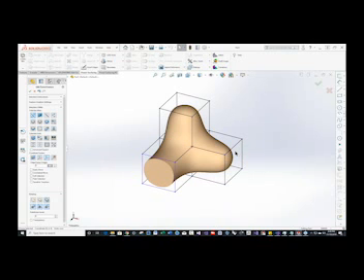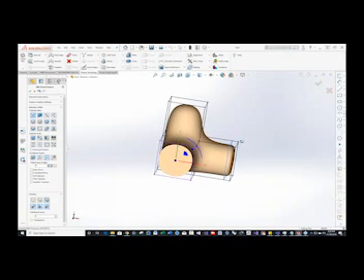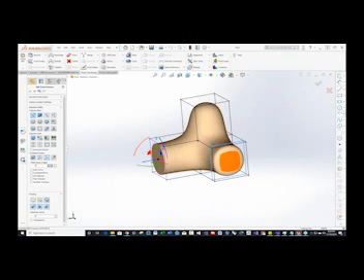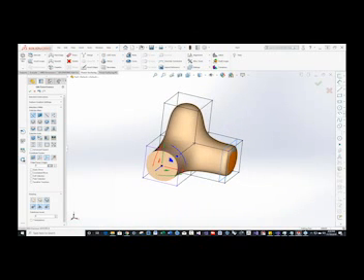Another way to attract the soap bubble is to insert additional edges. So I'm going to hold down on the A key, which is the insert loop key, and you can see it shows the loop where it will be inserted. And so if I click right there, I've inserted an extra loop in here, and you see now I have 2 edges that are close together that are attracting my little SubD soap bubble, and you can see it's much less rounded, and it's getting closer to looking like a fillet.